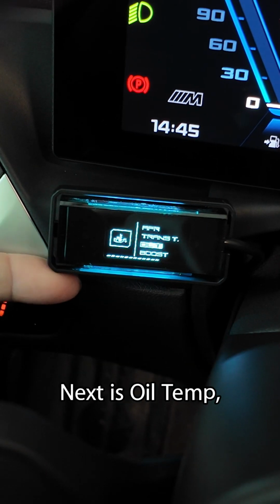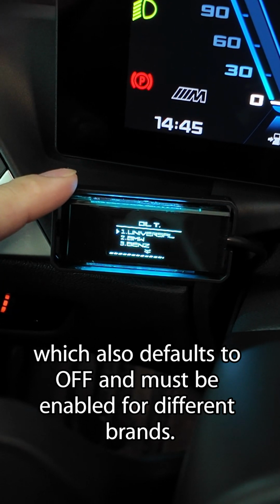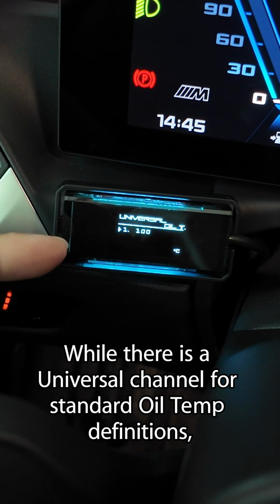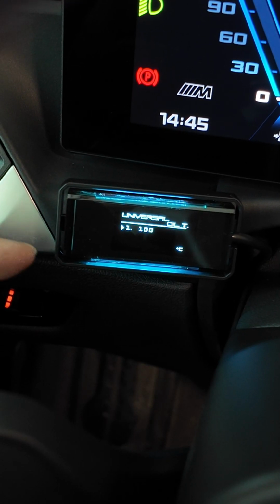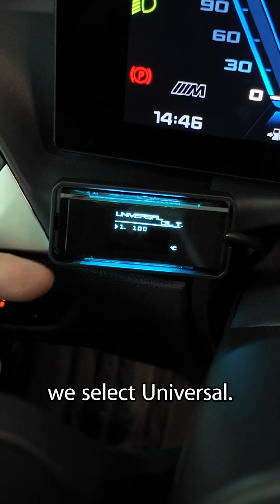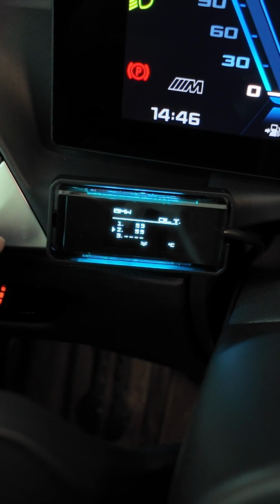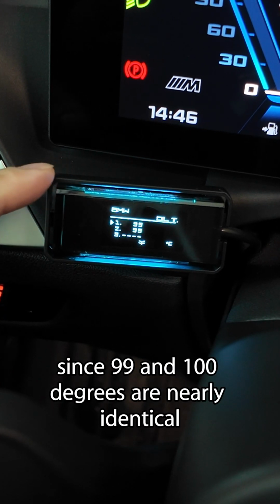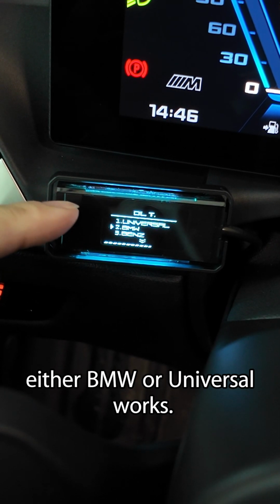Next is oil temp, which also defaults to OFF and must be enabled for different brands. While there is a universal channel for standard oil temp definitions, it may not be supported by every vehicle. Since this car has a standard oil temp channel, we select Universal. We can also verify under the BMW brand. Since 99 and 100 degrees are nearly identical and likely represent the same sensor, either BMW or Universal works.